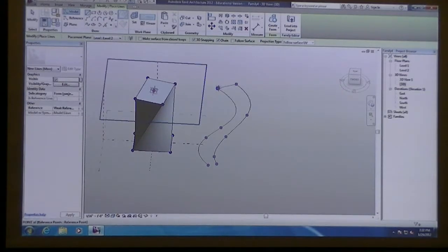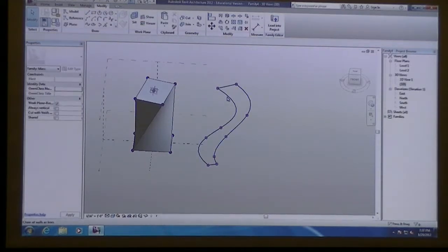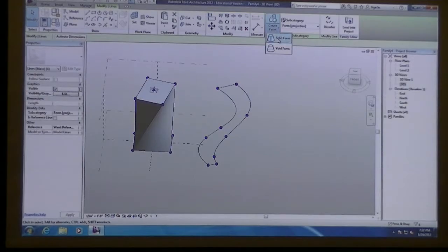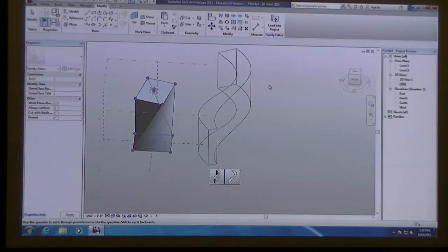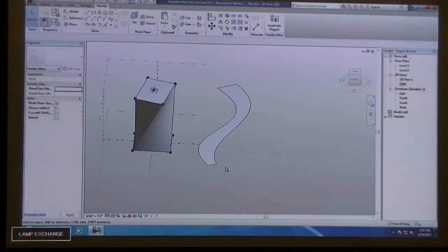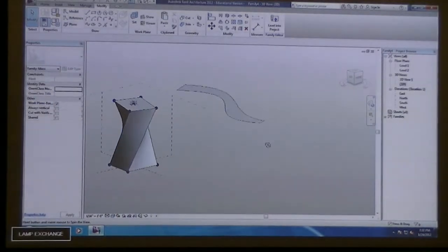If you close the shape, so far everyone knows how to create their parametric splines, because you've already been doing that with the complex shapes. You could do the same theory and have these in the same plane, and if you close them, you should be able to select it and say create form, and I get that option again for it to make an extruded surface or just a plane surface. So now I have a flat surface that could be your bridge.